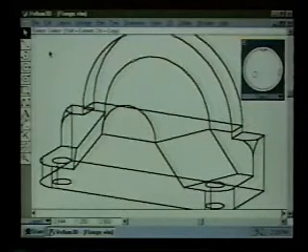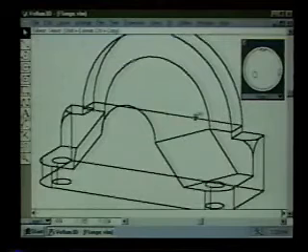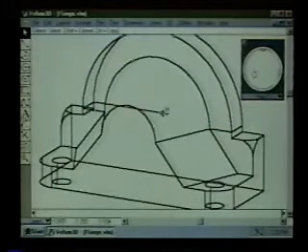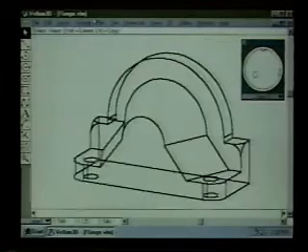Now, it turns out that for the surfacing, I want to get rid of this line and this one, because that would be a line running across a face, and it doesn't serve any purpose. So I want to keep things simple. So there's one on the back face, and there's actually a face here that has a couple of lines that I ought to get rid of as well. Now I know I have duplicates here, but that's okay, so I'll just get rid of those. And then let's go on with this. Let's say zoom all here.